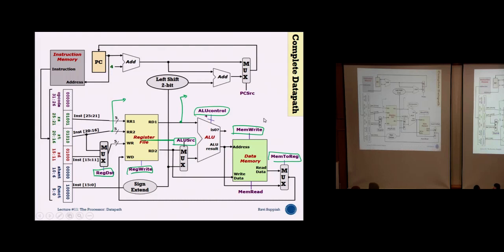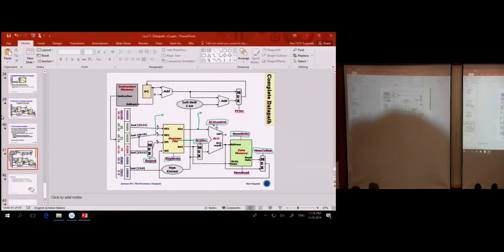For example, you mentioned branch equal, then they will shift 2 bits, so they multiply by 4, because it shifts 2 bits. Then you say here we decide whether the branch is taken or not taken. What do you mean by branch taken? Because the instruction is BEQ or something, right? For the BEQ, you must know whether it's equal or not. So even though I calculate the address, I still don't know whether the branch is taken. If the result is equal to 0, then the branch is taken.